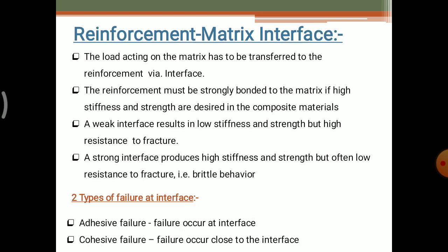Next one is the reinforcement matrix interface. So what is the main concept of the reinforcement matrix phase? That is the bonding between the primary and secondary phases. The load acting on the matrix has to be transferred to the reinforcement via the interface.